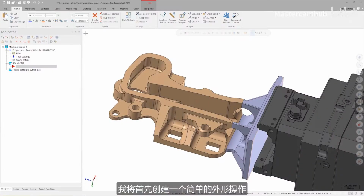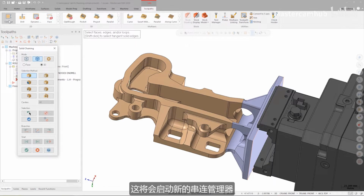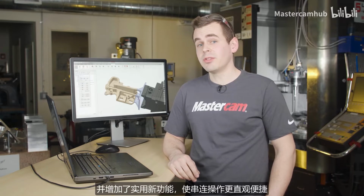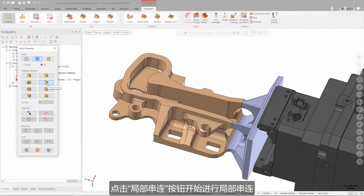I'm going to start by creating a simple contour operation by going to the Toolpath tab and launching Contour from the 2D Toolpath gallery. This will open the new Chaining Manager, which has been completely revamped for Mastercam 2020, to make it easier to use and to accommodate the new functions that have been added. Let's start with the partial chains by clicking the Partial Loop button.